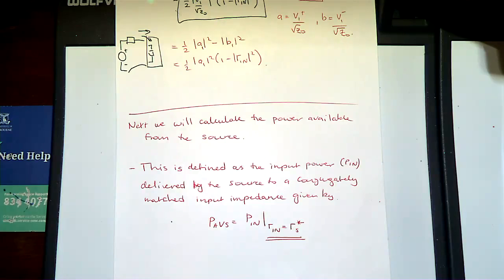Okay. That's when the maximum power occurs, right? And we talked about that maximum power transfer occurs when the load is conjugately matched to the source impedance. And specifically we said that theorem only applies when the source impedance is fixed. In this case, we've got a signal generator with a given source impedance.